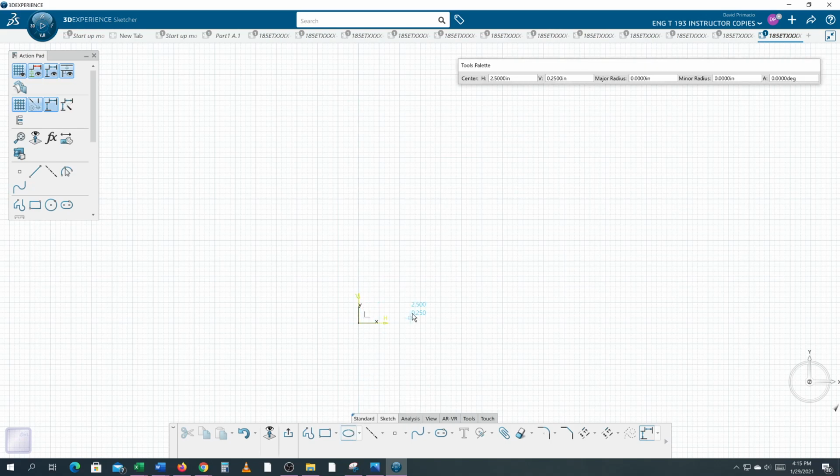I can count it all out, or what I could do here is create an ellipse, and it needs a center point of the ellipse. So it's asking for a center here. Height. There we go. Height is supposed to be 48 inches, or 2 times 12. 4 times 12 for 4 feet. Divide that by 2 to get me in the middle, and then I'll hit tab. So let's say vertically I'll make it 6 feet, so that'd be 12 times 6.